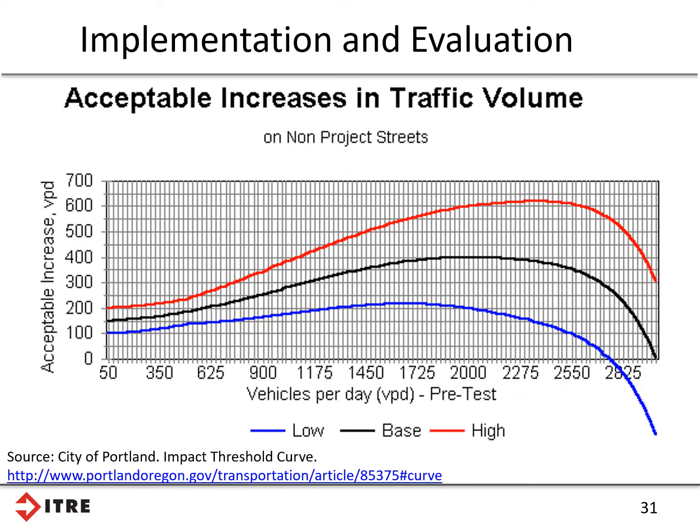When we're looking at the implementation and evaluation of traffic calming, it is a well-accepted retrofit. A lot of communities, if you follow neighborhood forums, are asking for things that may not be appropriate for the location, but they may be asking for speed bumps or speed humps or more stop signs or lower speed limits. So there's already an awareness that traffic calming can happen and can be effective. There are many alternatives. Traffic control devices can be used. They're generally not as successful as some of the more physical elements to have the desired impact.